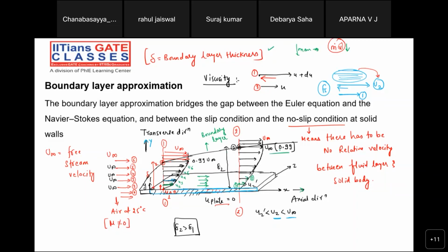Till now, we have not answered any question. I'm just telling you why this boundary layer formation is happening. So please just make a note of it. After that, we have a lot of interesting phenomena related to this boundary layer. The moment you get the boundary layer, everything is sorted out. Of course, this is a very imaginary thing. It's just our imagination, or maybe it is not visible in experimental conditions, but still we are very happy with that because it demarcates between the two flow domains. One is the viscous domain and the other is the non-viscous domain, which we refer to as the inviscid zone.